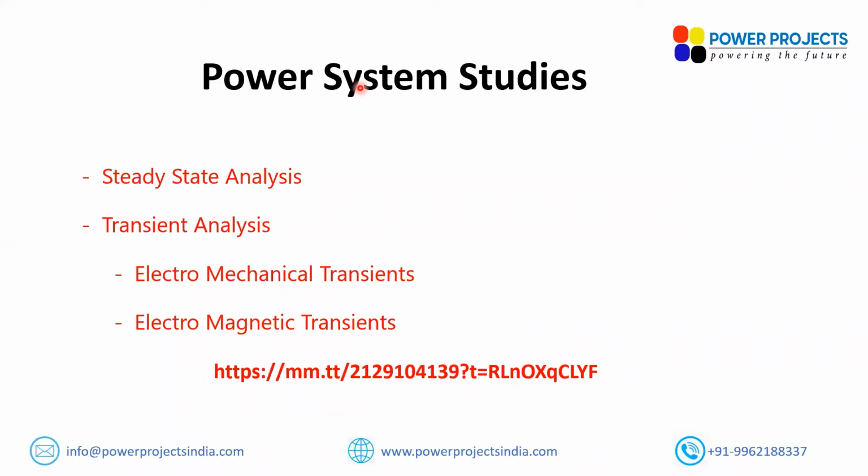When you are talking about transient analysis, if the breaker opens, how much time the breaker is taking to open, etcetera, if you want to study that with respect to time, then it is transient analysis. If you are assessing any system's performance at a single moment, an instant, then it is a steady state. With respect to time, it is a transient analysis. After talking about transient analysis, we have to talk about two important transients: electromechanical transients and electromagnetic transients. Let's first talk about electromechanical transients.